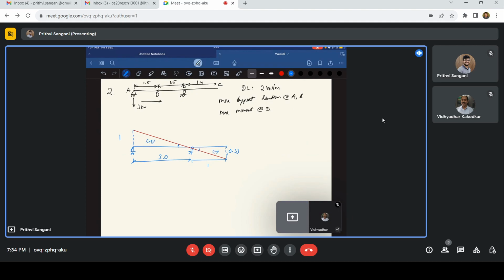Okay. Again, in the shear force, the sign convention is of more significance, but at the end, we'll consider both the directions. Only in the bending moment do we need to strictly follow the sign conventions, because that tells us which side of the beam is in tension and which side is under compression.